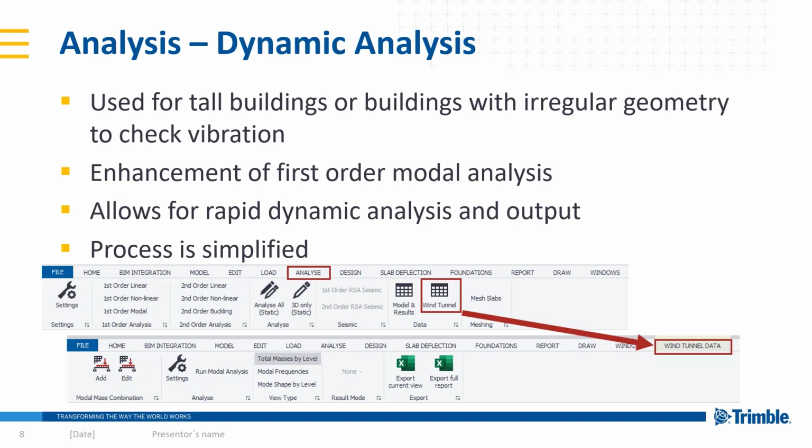First order modal analysis, or previously first order vibrations as it was called in early versions of the program, has always existed within the program. However, the steps required to successfully perform a first order modal analysis were located in different parts of the program. You had to manually create the combination. You also had to remember to set the type of combination correctly. The analysis had to be performed separately, and also result output was separate from the input and the process.